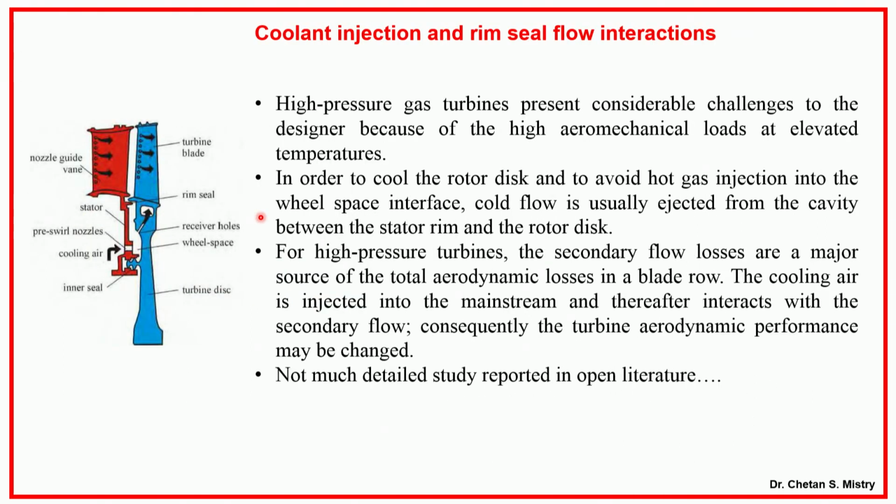This is what we say coolant injection and rim seal flow interaction. We know for the HP turbine, the flow will be entering at very high temperature. If we do not allow it to cool, it will melt. So in order to provide that cooling, we extract air from the HP compressor, and that is what flows through the rim seals and enters inside these holes.